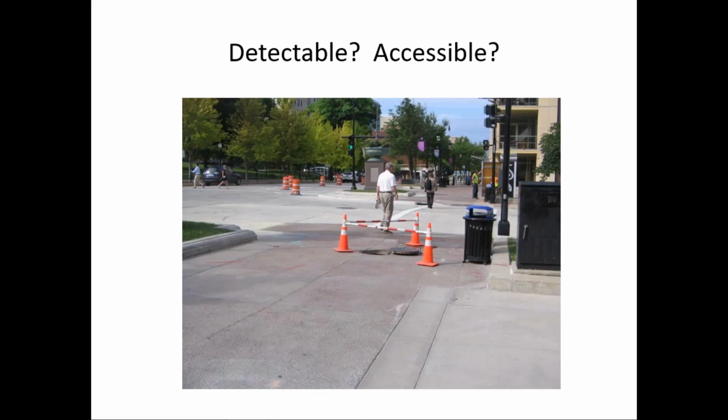And then one more, this is in Wisconsin a few years ago. Notice, and I don't know the whole story, but I was here about a half an hour talking with someone, and a crew came in, a 3-person crew. You can see they removed the manhole cover. Two of the crew members went down below grade. They installed some traffic control here. And in fairness, for like 90% of the time I was there, the third crew member was kind of standing here, I guess both being able to assist those below the surface, but also serving as a spotter or providing warning for pedestrians in the area.